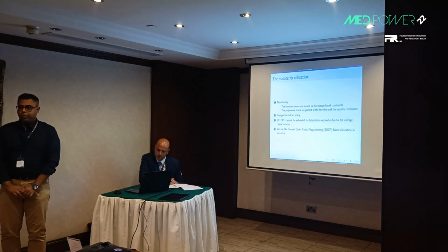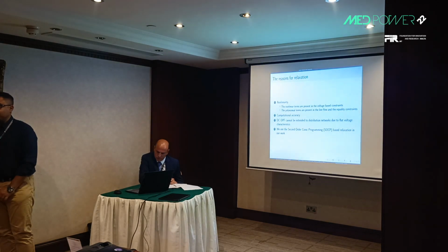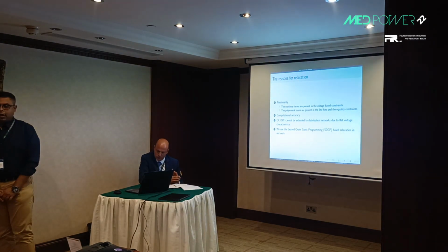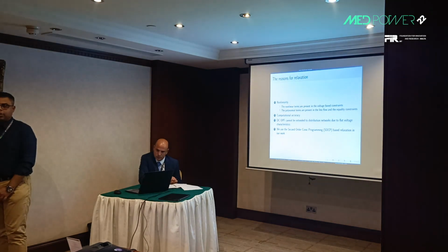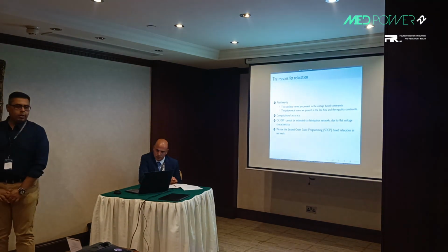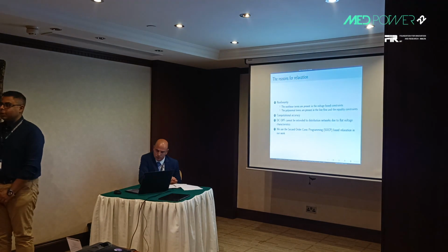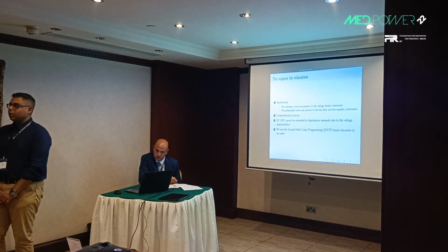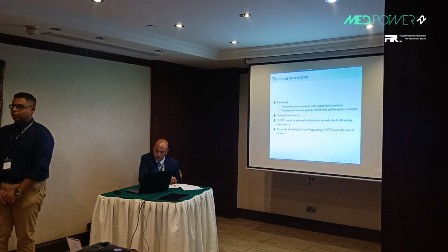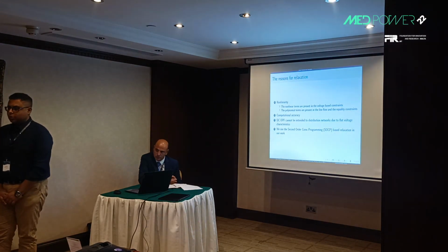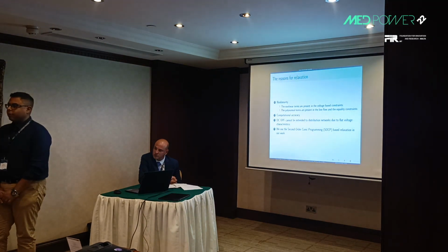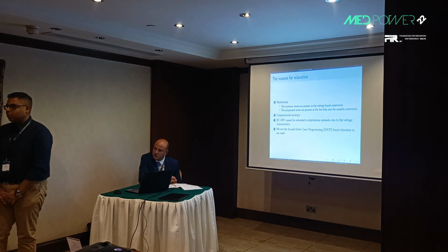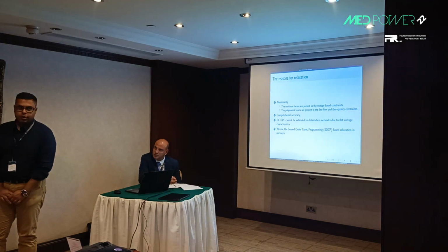Now, if we wish to have better computational accuracy, we generally seek to linearize our OPF. One way is to use the DCOPF, but with the DCOPF we have one issue: flat voltage characteristics, and when we solve a loss minimization, DCOPF cannot be very well suited for distribution networks.